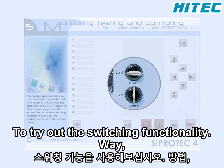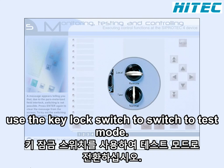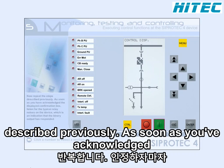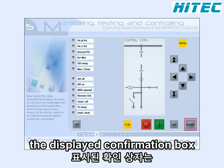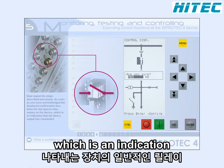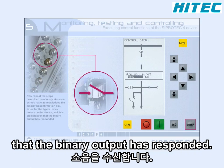To try out the switching function anyway, use the key lock switch to switch to test mode. Now repeat the steps described previously. As soon as you've acknowledged the displayed confirmation box, listen for the typical relay noises on the device, which is an indication that the binary output has responded.